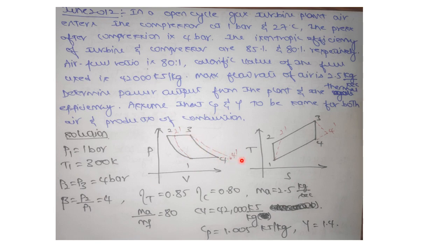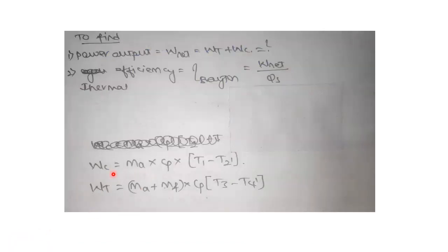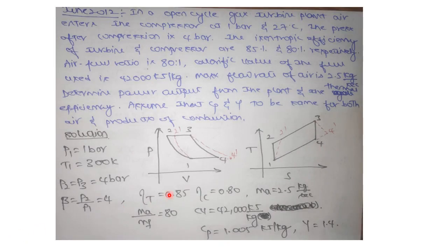That is all fine, but this is very interesting. What is the working fluid in the compressor? In the compressor only air enters. Air will be compressed up to state 2. From 2 you will be adding fuel. The fuel gets burned, so mass of air plus mass of fuel you are adding will reach state 3. That means the turbine is handling both air and gases, whereas the compressor is handling only air.